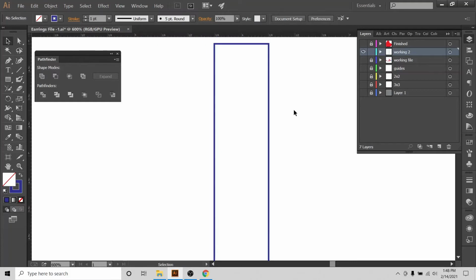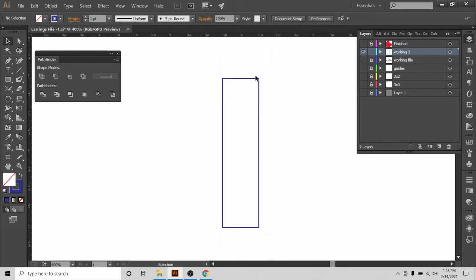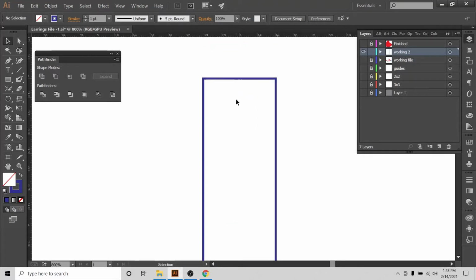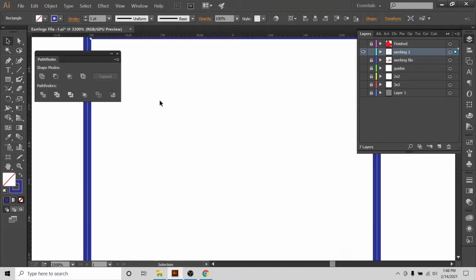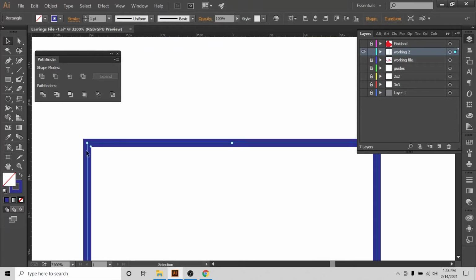Now, as a product designer, we are told to make shapes more rounded, so they are easy to cut and good to look at. So what I'm going to do, this is a good shape, but I'm going to make it even better. For that, I want to show you a close-up. So I'm going to select this box, and you see this round point with the anchor point.